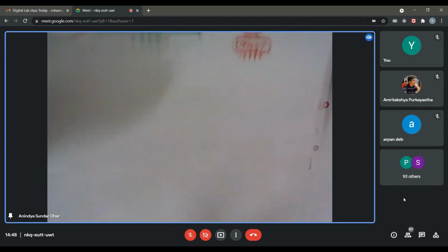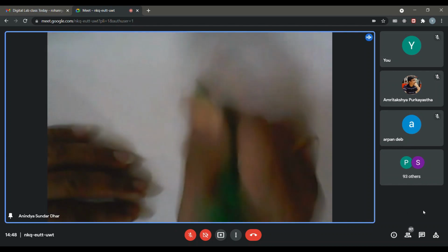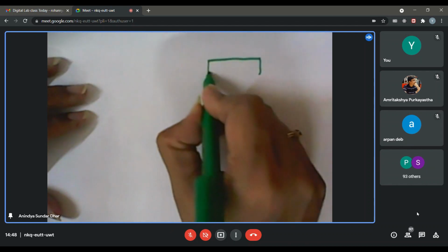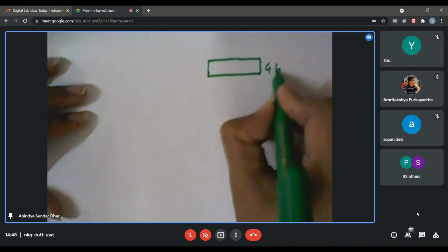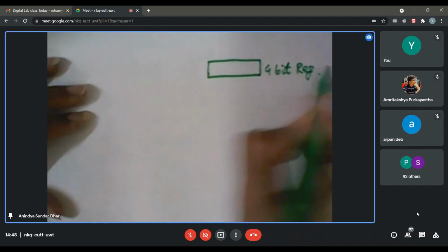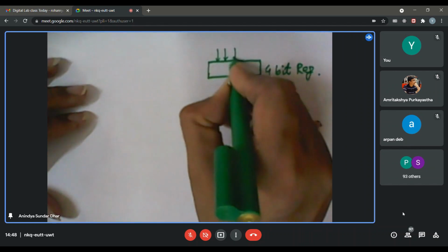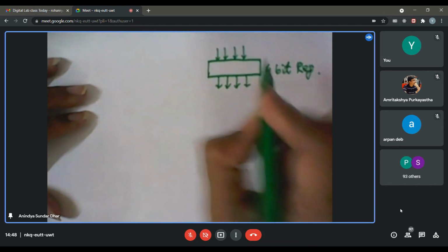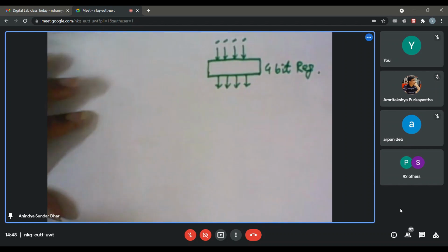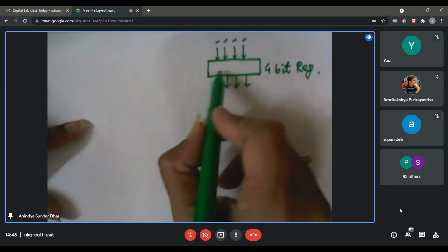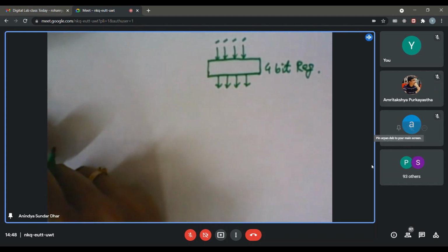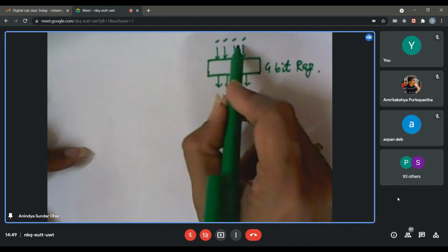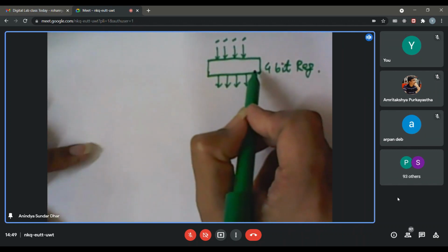So just let me define a little bit about the register, what it is. So if I think about, let us say, a 4-bit register, as the name suggests, it would be able to memorize a 4-bit number. So it must be having 4 input lines, 4 output lines. So whatever I will make available at these 4-bit lines, a pattern of zeros and ones, it will be able to memorize it. Now, how do I indicate that I want to latch these numbers right at this moment, that even if after that it is not available, I change that one, you remember what I have put earlier.